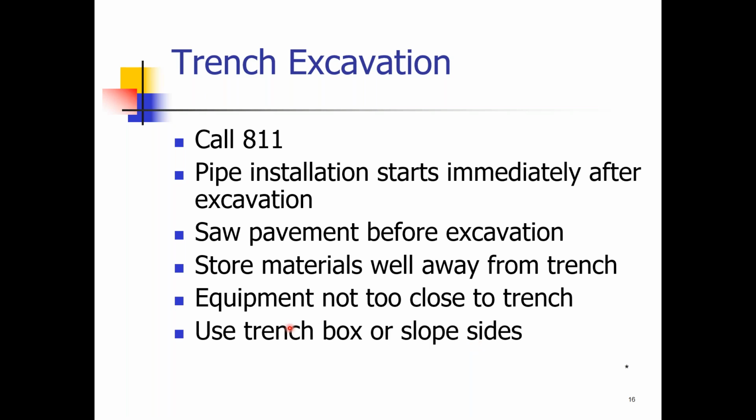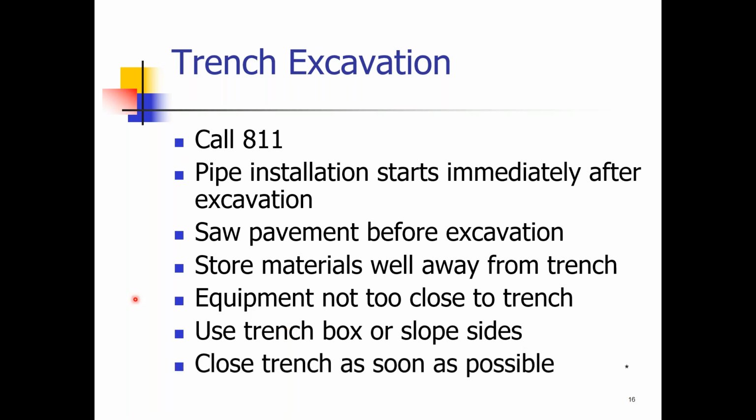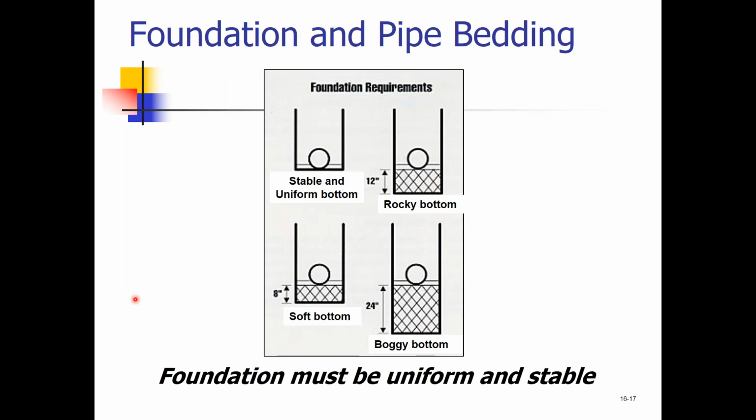It's probably a good idea to go ahead and use a trench box to keep that soil back on either side so that our workers can be protected. And by all means, as soon as you're done, get that excavation area closed as soon as possible. We talked about bedding just a couple of slides ago, and a foundation.